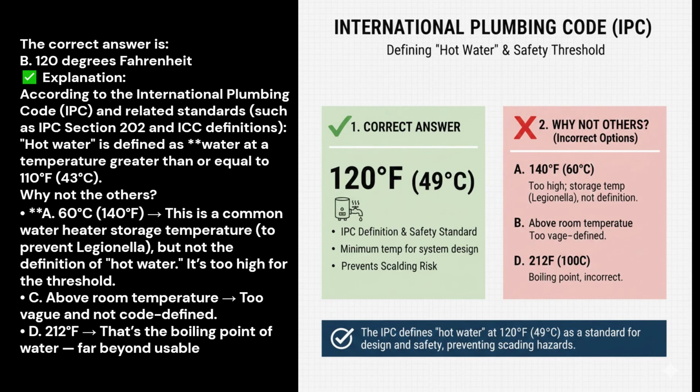That the proper amount of solvent cement was used in making the joint. Explanation. When joining PVC or ABS pipe with solvent cement, a key visual indicator of a properly made joint is a continuous, uniform bead of solvent cement around the pipe at the fitting's edge. This bead confirms that enough cement was applied, the cement was distributed evenly as the pipe was inserted, and a complete seal has likely been achieved.